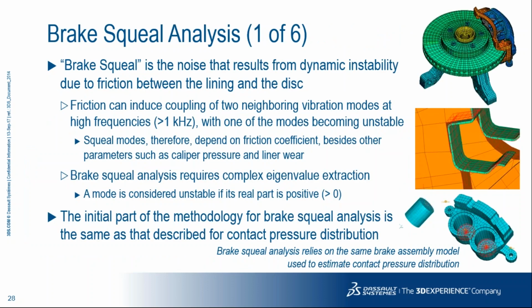Coming to brake squeal analysis, which is a major analysis that brake industries, brake lining and allied industries usually work on. So brake squeal is the noise that results from dynamic instability caused by the friction between the lining and the disc, and this instability can create noise, which is commonly known as brake squeal.